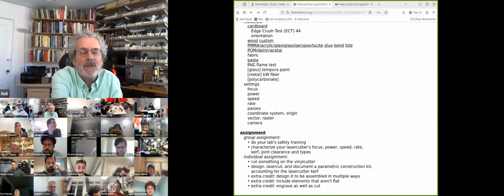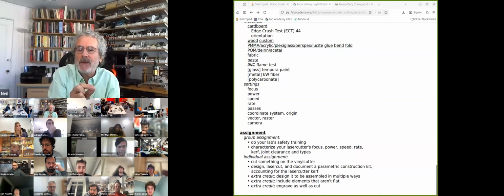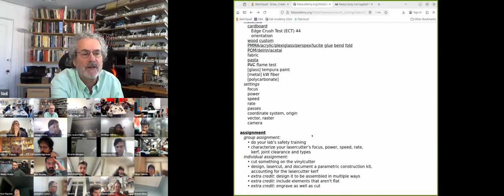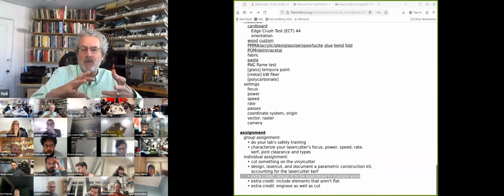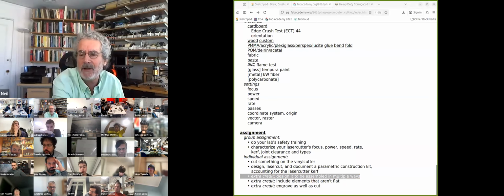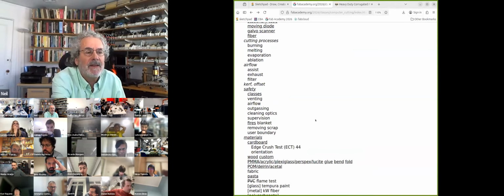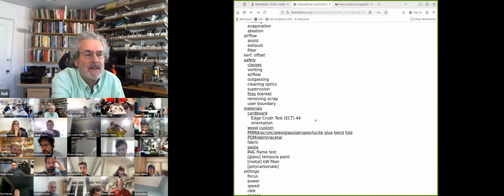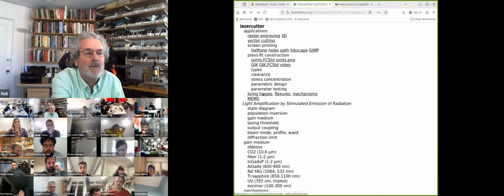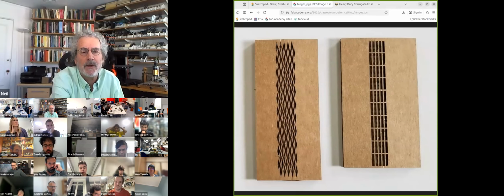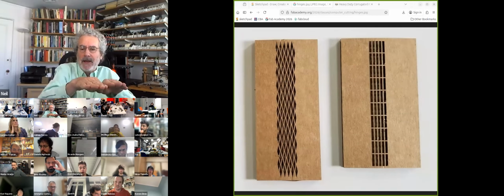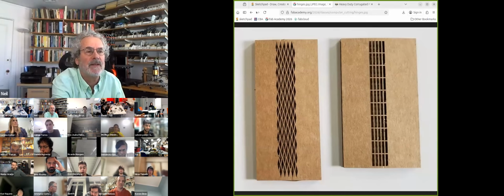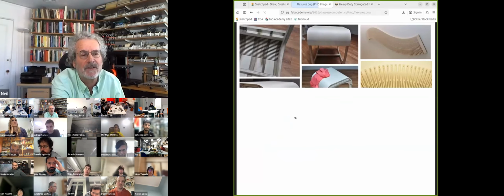But then I want you to design a construction kit. I want it to be parametric, so you can adjust to the materials, account for laser cutter kerf. A fun design task is design it so you can assemble it more than one way, not just a box, but a general kit. And then another thing you can do is, these are called living hinges, where you cut a pattern in the cardboard and it lets you bend the cardboard up into 3D. And then you can design flexures around that.